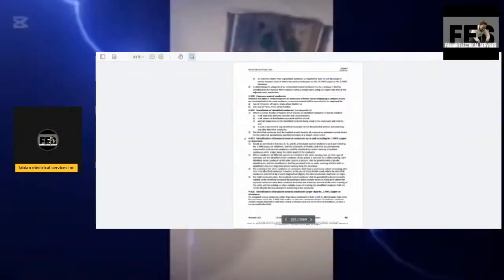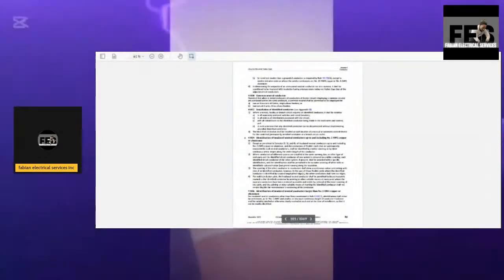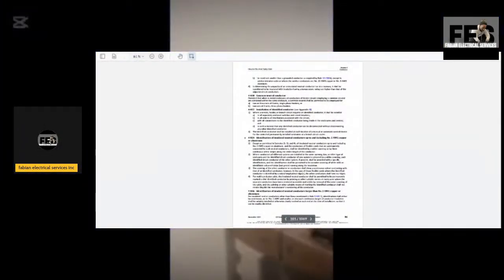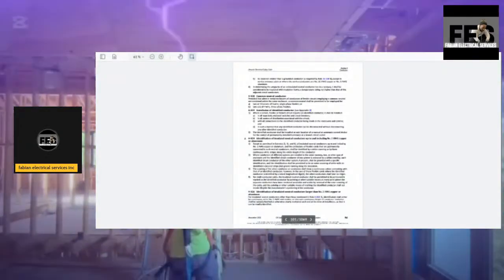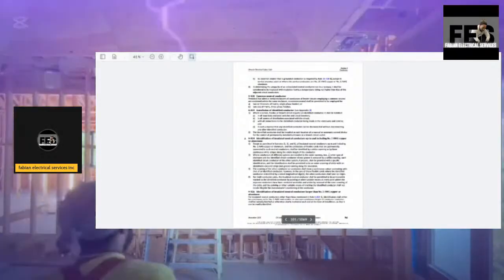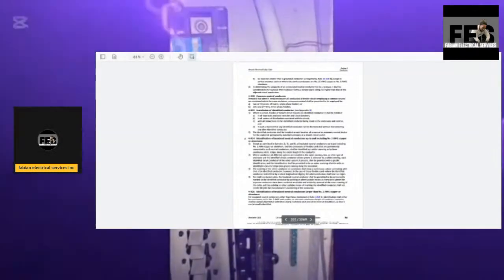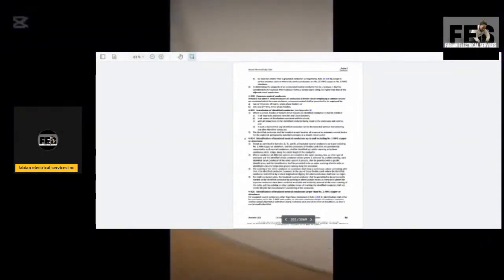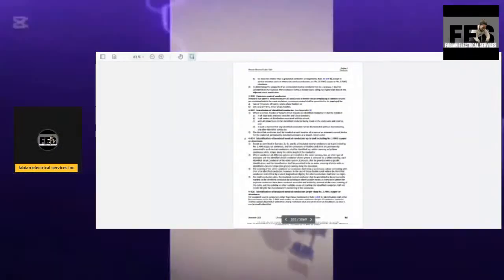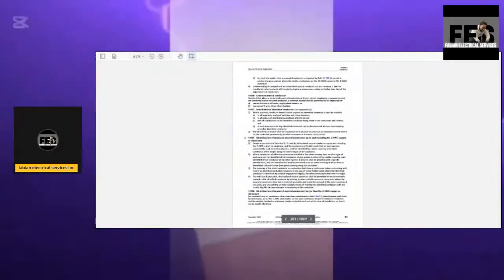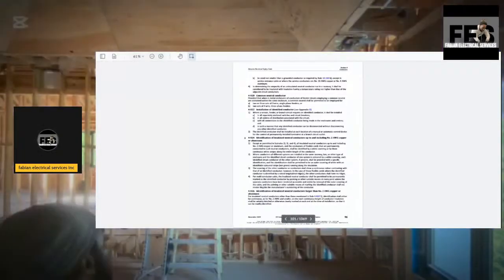It says all insulated neutral conductors up to and including number 2 copper or aluminum, and the conductors of flexible cords that are permanently connected to such neutral conductors shall be identified by a white covering or by 3 continuous white stripes along the entire length of the conductor. And that's how we basically identify our neutral conductor. In the previous video, like I said, you're going to see it there. I am identifying my conductor with white tape. That's where the rule comes from, right here.